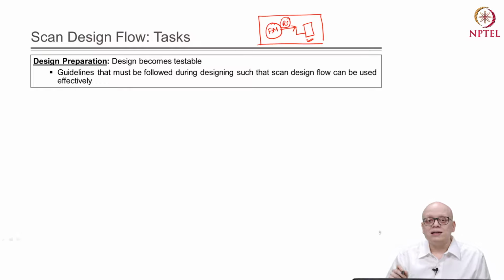There are other guidelines which need to be taken care of while making our design or implementing the scan design methodology in our design. So, these things must be taken care of during the earlier stages of our design implementation, while writing the RTL and so on.